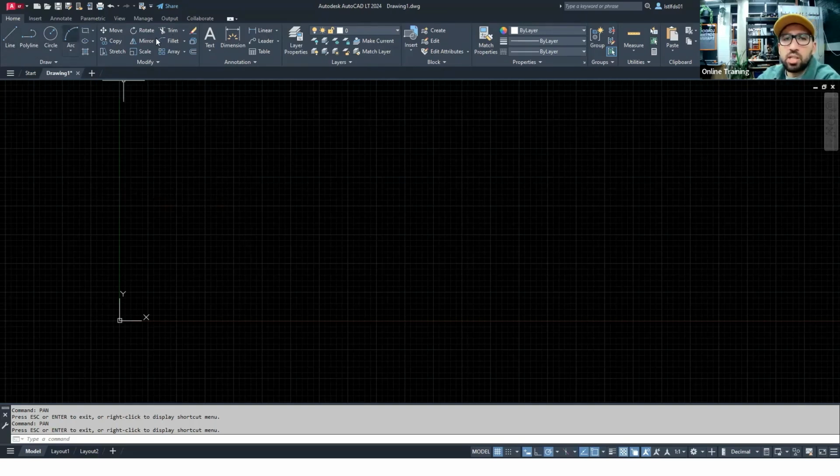I rarely use these commands by clicking on the buttons because I use shortcuts. Shortcuts are substantial on AutoCAD. There are quite a lot, but they're quite easy to memorize as well. They are usually the first letter, 2 letters, or 3 letters of the command you want to use. Line, you just write down L, enter, and you are in the line command. Circle, it's C, enter, and so on. They might overlap, so you might need to write down more than 1 letter, but don't worry, when we practice throughout the course, you're going to memorize most of them. In the resources folder, I have an A4 sheet that has most of the commands. You can print it out later on, keep it on the side. You can just use it as a reference.